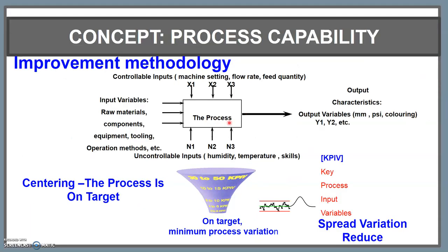All of these are variations for a process. You can see there are so many variations here. If you have different variations and different settings, the product that comes out will have different values. Different value is called variation. So the purpose of process capability in this chapter is for you to narrow down all the variations so that you can produce a stable process to produce quality goods.